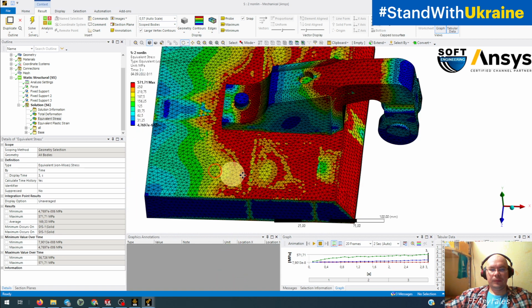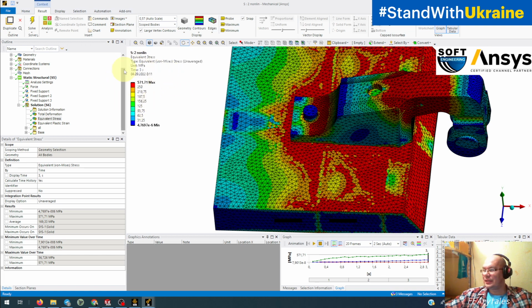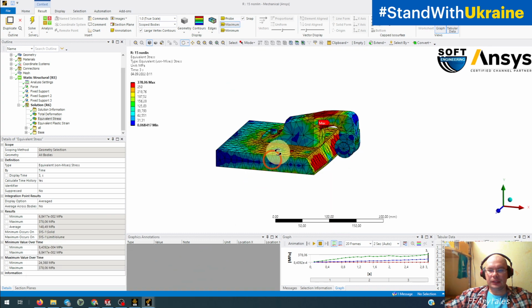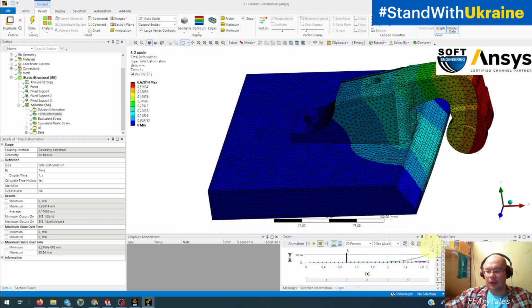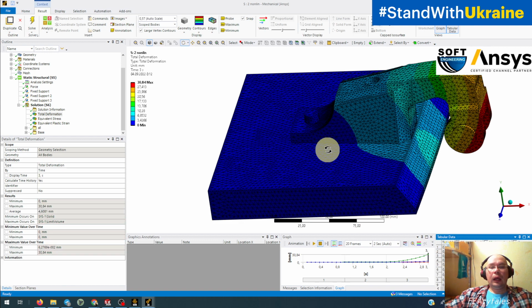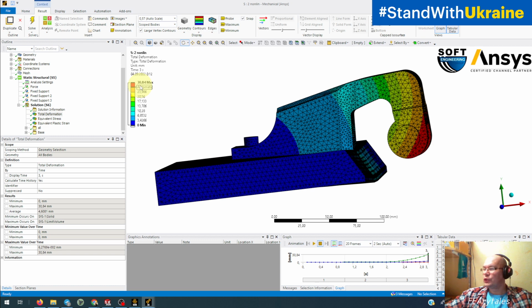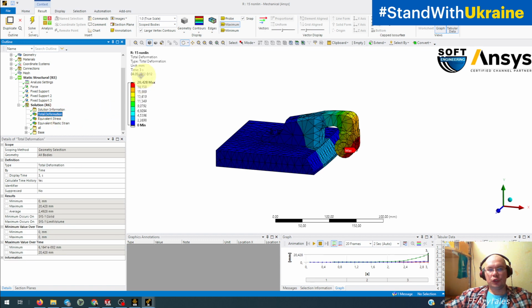And we have a result of stresses with the nonlinear solution almost twice, okay, 1.5 times bigger, with the same load as on this mesh. And we have bigger deformation. Just a moment. We have much bigger deformation. It's almost 31. And here we have 20.5.